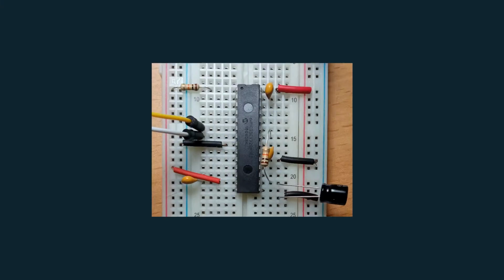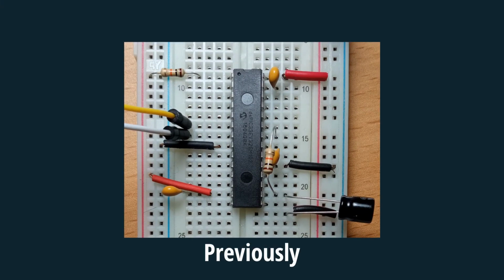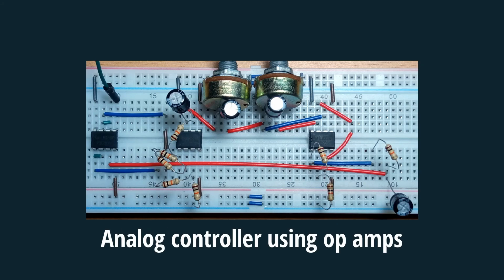Hi, previously I designed two discrete compensators to improve the step response of a first-order RC circuit. This time, I went fully analog by using only operational amplifiers, and for that I used the frequency response design method based on Bode plot.